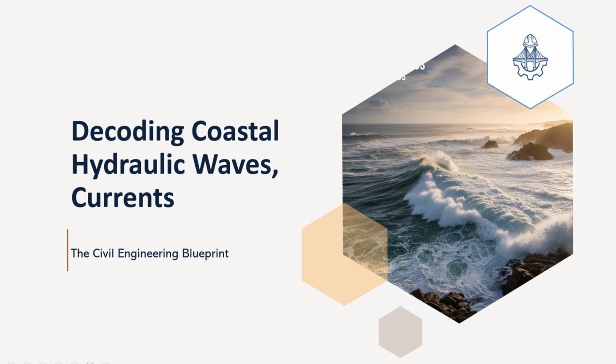This equation is incredibly important because it shows that wave energy is proportional to the square of the wave height, H. This means even a small increase in wave height, say doubling it, leads to a fourfold increase in the energy content and thus its potential for damage. This quadratic relationship is a critical insight for engineers assessing risk. It's the fuel driving all the processes we're discussing.